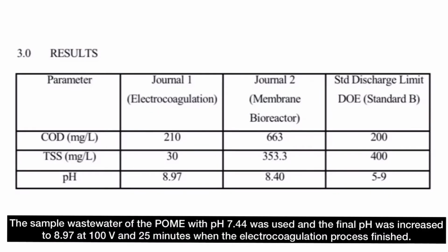The sample wastewater of POME with pH 7.44 was used and the final pH was increased to 8.97 at 100 volt and 25 minutes when the electrocoagulation process finished.